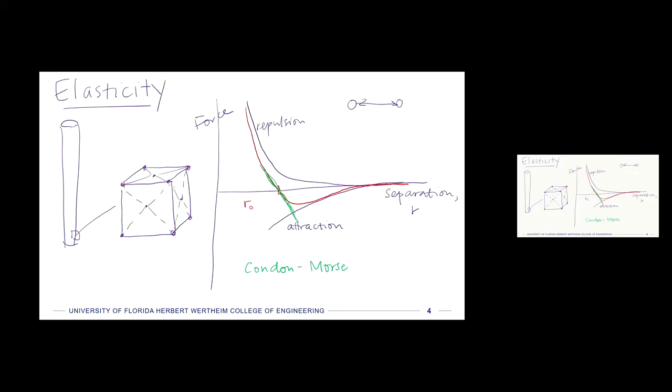I'm going to try to bring that in through the class so that you know a little bit about the scientific genealogy of the concepts that we're learning about. And so if we draw that linear approximation, then we can say that if we apply that through the whole component, then all of these tiny fractional changes will add up to the overall change in length, okay? And so you can say that the overall change of length of a component is the sum of all of the individual stretching or length changes from all these individual cells.